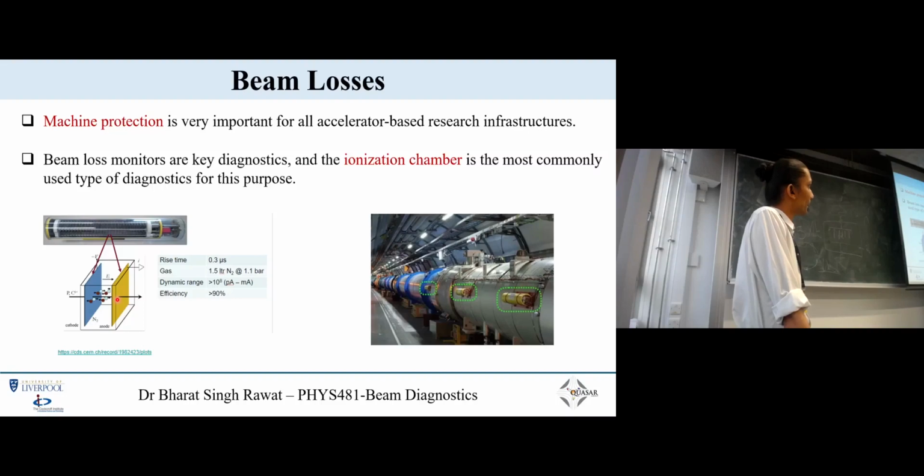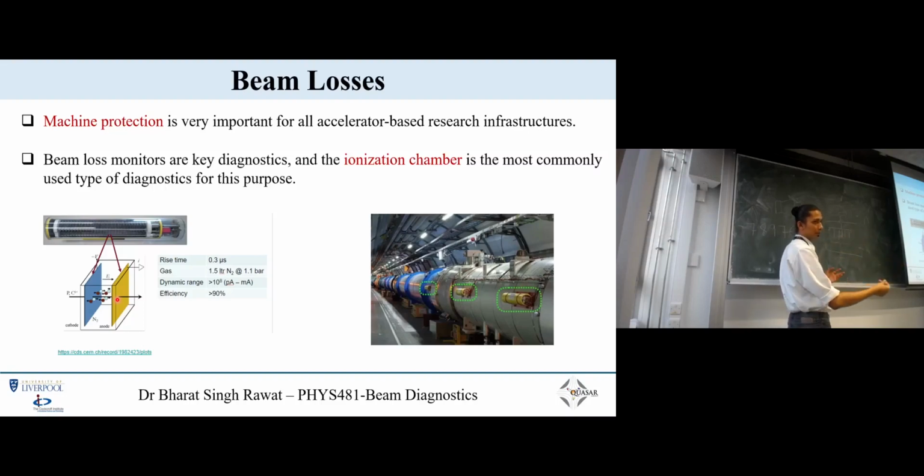The basic reason is that if the electric field is not very high, you give enough time for these electrons to combine with your ions, and recombination occurs, and it again becomes your neutral gas. So it does not have enough time to reach the anode, and before that it becomes a gas. So you lose your measurement. If it is very high, all these electrons move very fast towards the anode without getting recombined. That's why you need a very high electric field.